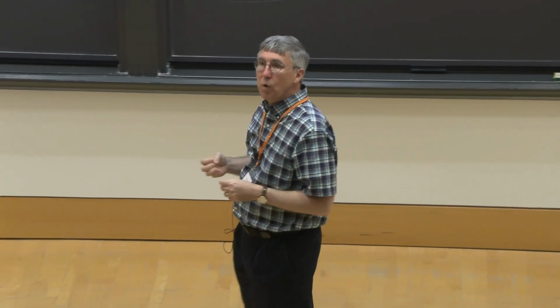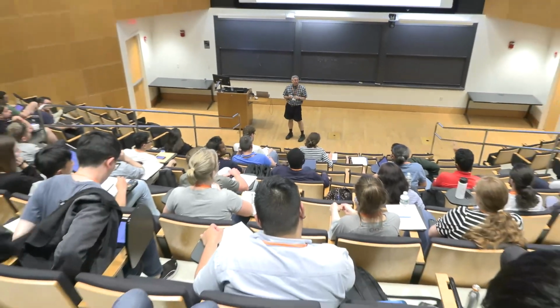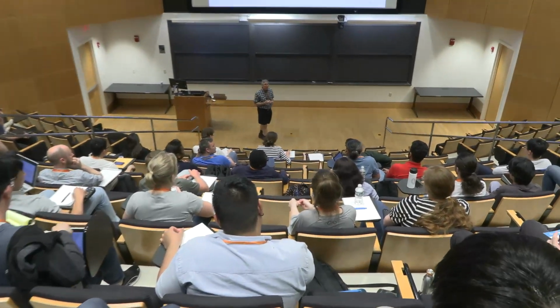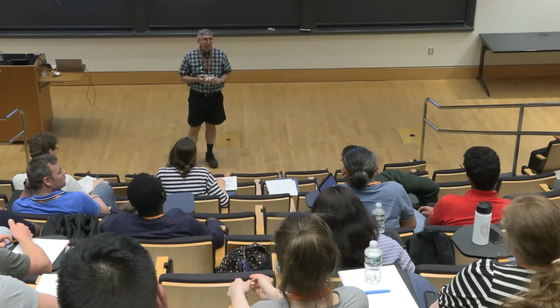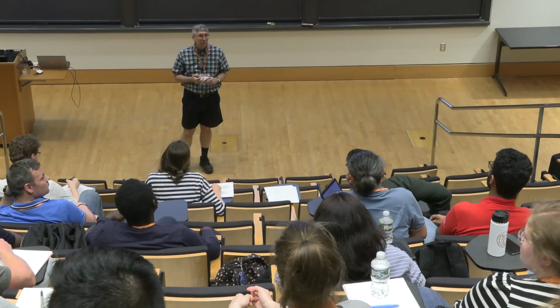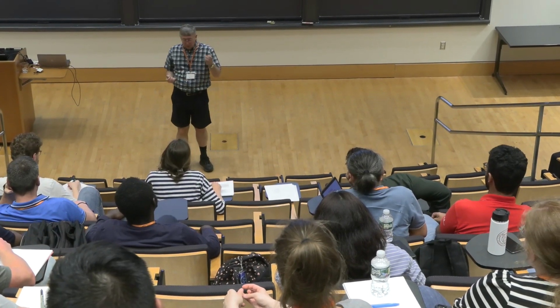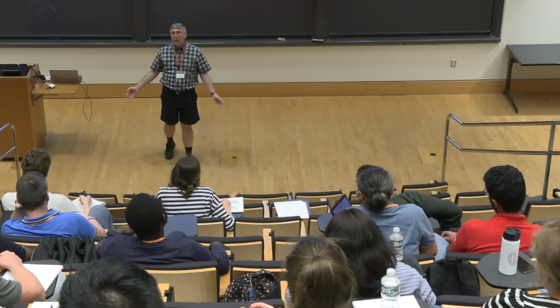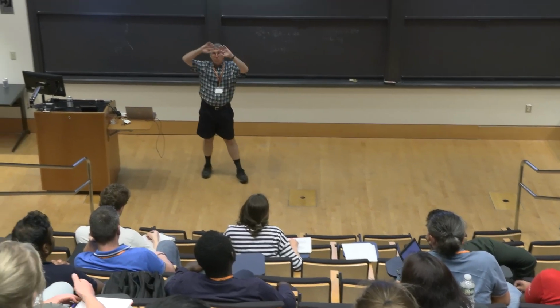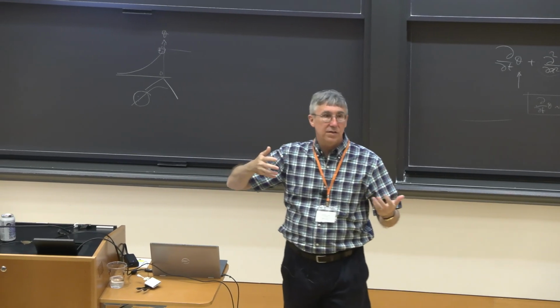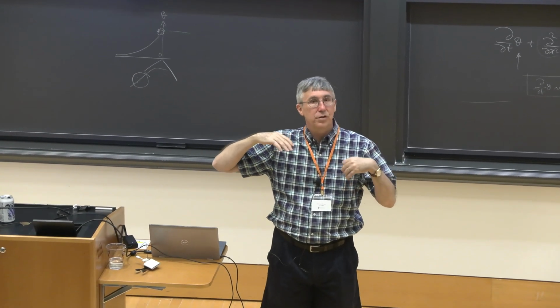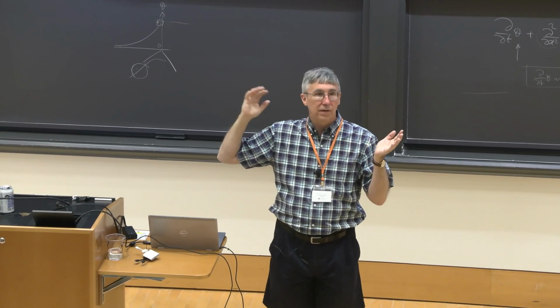Is there any other reason why you might want to simplify it down? Yeah. Maybe they want to capture a specific phenomenon, let's say like ignition delay time or laminar flame speed, so there is no need to include the formation. Yeah, so sometimes your model is very ambitious to predict a lot of things, but maybe your actual application is much simpler than that, so you don't need all that stuff in there, and it's just chewing up computer time for no benefit.